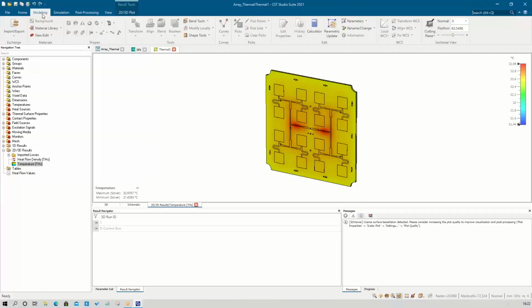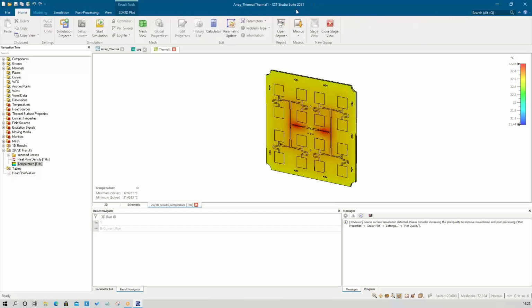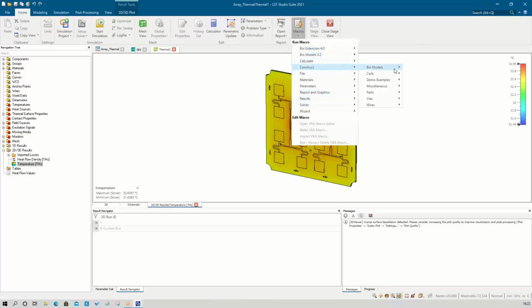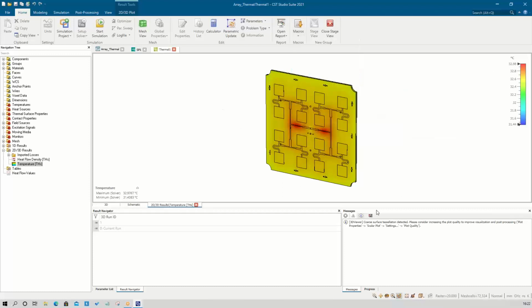If I increase the power, you will have more temperature there. So if the temperature is there, I have to use some method like cooling, or I can simply add a fan to reduce the temperature. You have an option here, a fan. If you enable the fan, then I will get a fan over here. I can use the flow thermal analysis and reduce it. So CST is a package where you are not just limited to designing the antenna, it's more than that. That's the reason you can get a lot of publications in CST than any other.